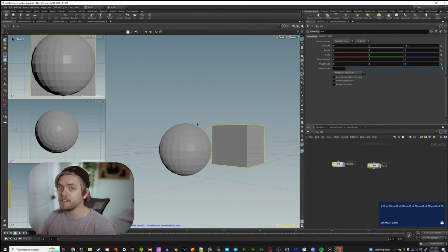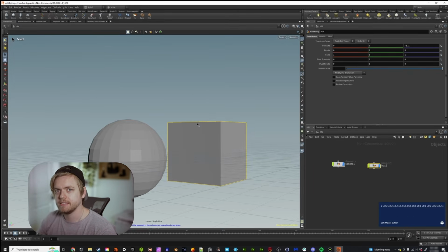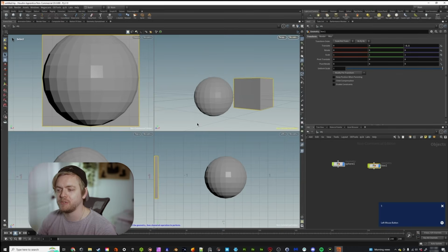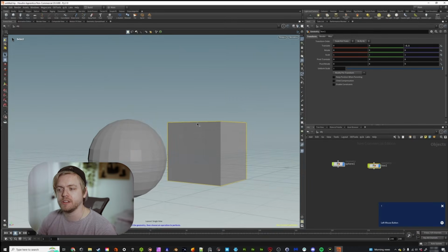But you can also very quickly toggle between these with control and the different numbers. For example, control 1 will give you 1 split, right? 1 main view in the scene view window. Control 2, you guessed it, that's 2. 3 is 3, 4 is 4. There is no 5. I just tried it, just out of curiosity. It doesn't exist. So this is a real quick way for you to jump between different setups that you might want for various different operations inside of Houdini. Very, very helpful.